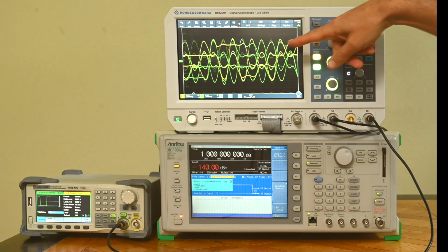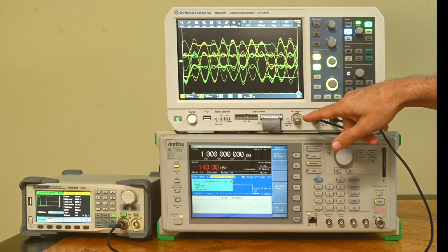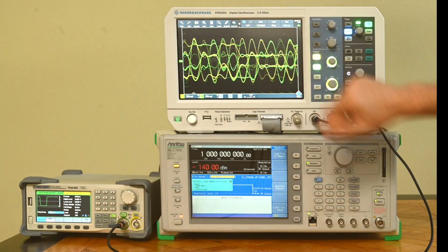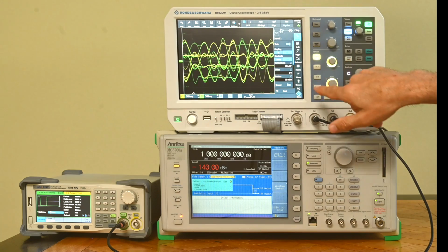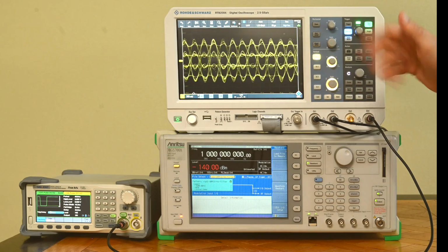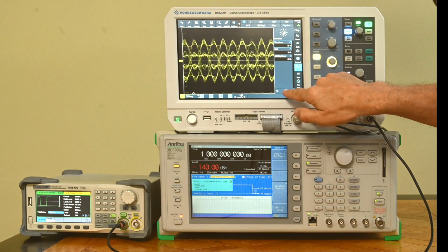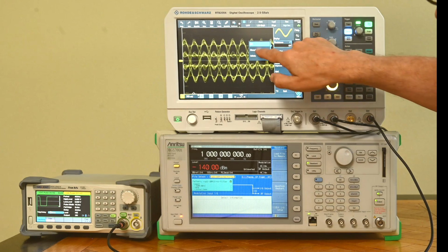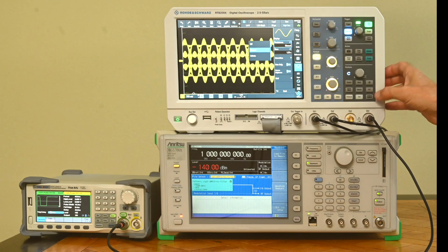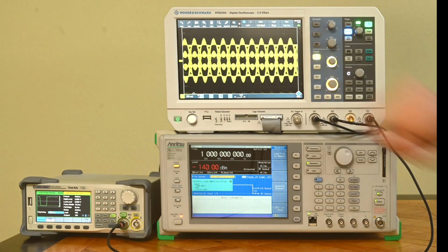And as you already might kind of see, there are 4 distinct levels, both for the I and the Q signal. I'm not even sure they're on the straight line, but we can kind of distinguish 2 signals. I'm going to turn off one of the channels, so we just got channel A here. Now, depending on the synchronization that we have here, I'm actually going to use a little bit of persistence. Yeah, that's how I like it. We can see kind of these levels coming in, and we can see the periodic character of the waveform.